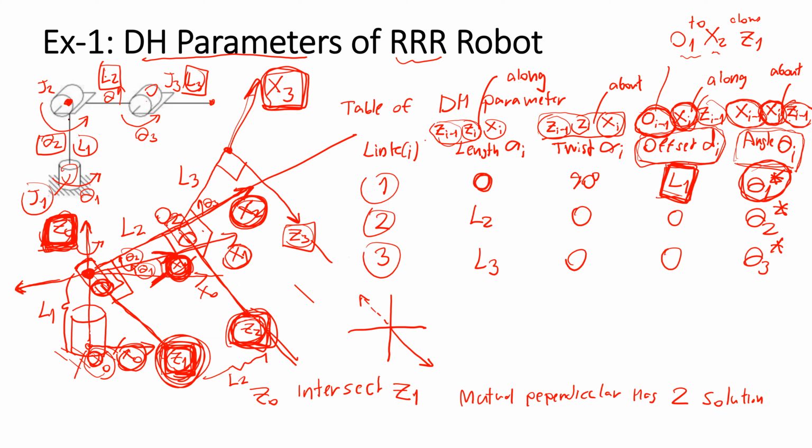Yes. Here also will be 0. Yeah, it will be easy in the calculation, but when you want to relate your mathematical expression with your physical system, you should keep in mind that the global frame, the base frame of the robot in the physical system, is not on the floor, but somewhere above the floor by the length L1. Just only this.